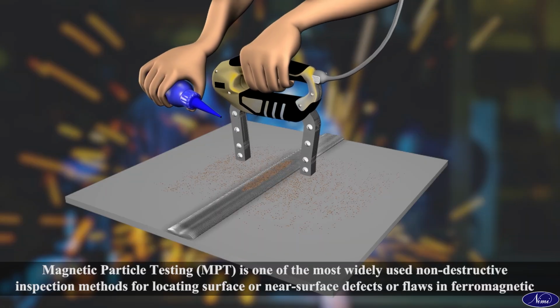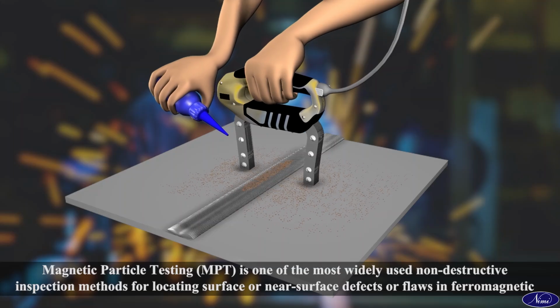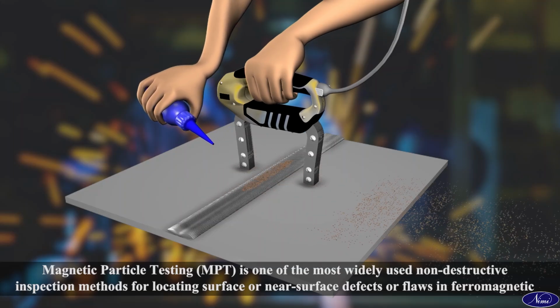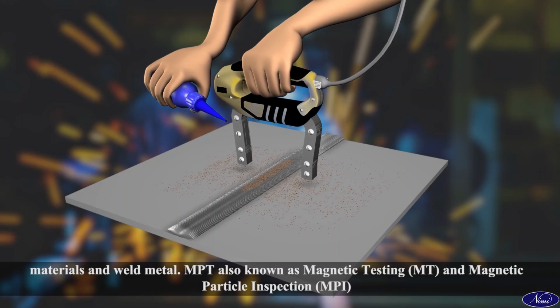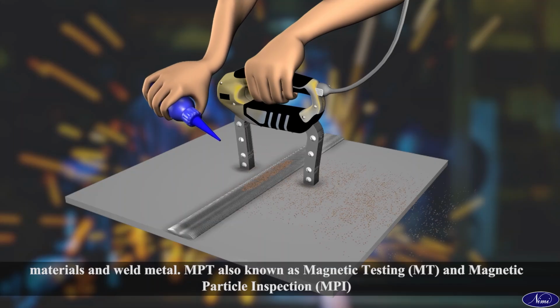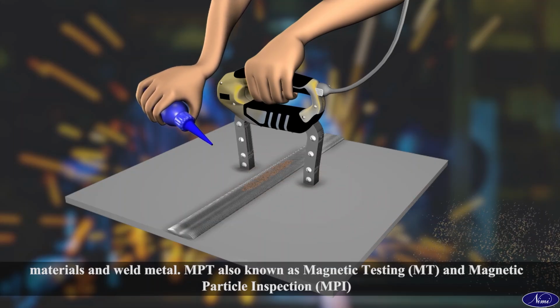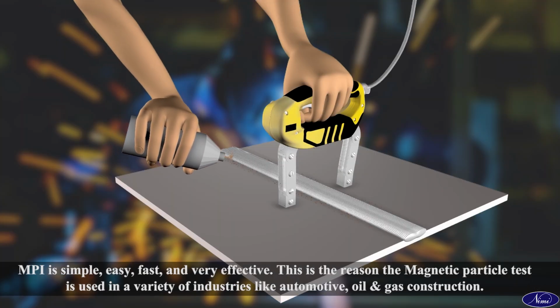Magnetic particle testing (MPT) is one of the most widely used non-destructive inspection methods for locating surface or near surface defects or flaws in ferromagnetic materials and weld metal. MPT, also known as magnetic testing (MT) and magnetic particle inspection (MPI). MPI is simple, easy, fast, and very effective.